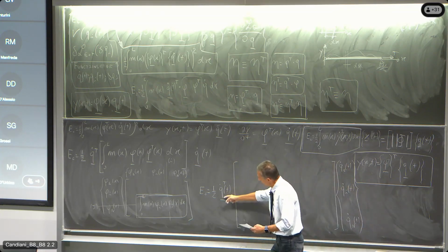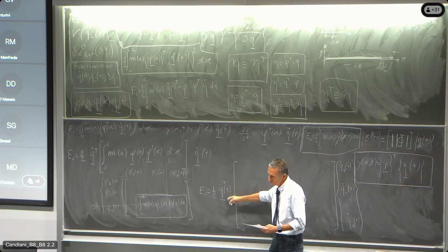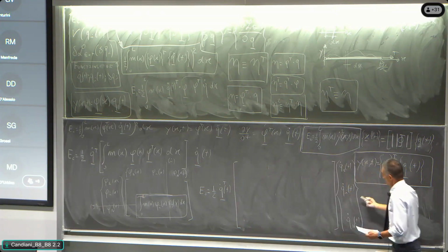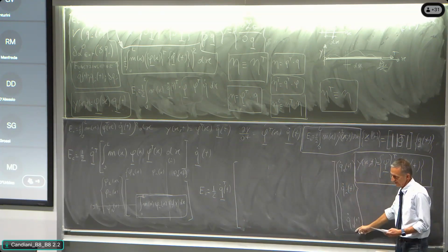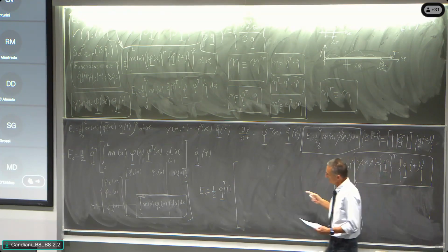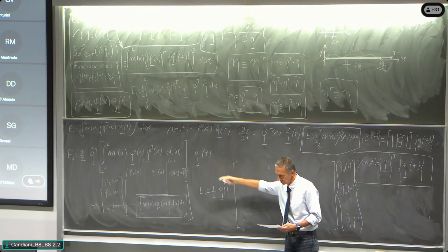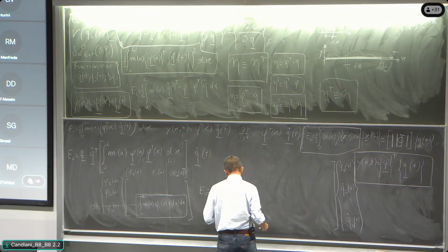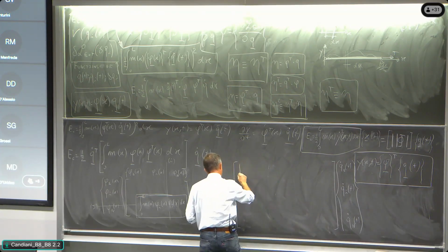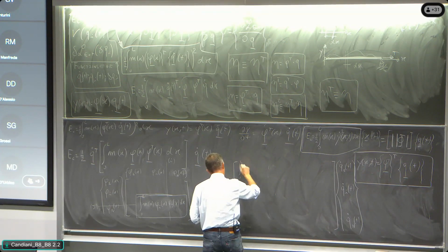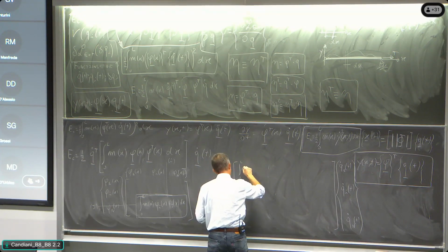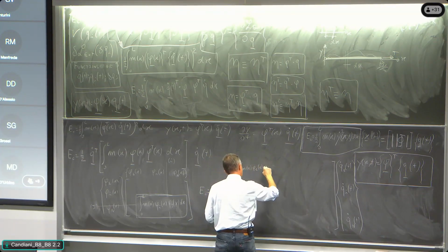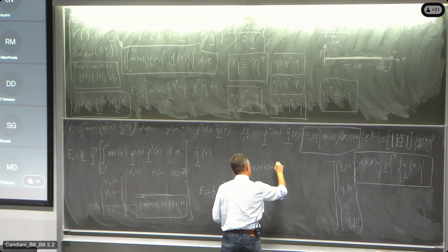Now here I do not write the vector q1 dot q2, but I write q transposed, knowing that q is the vector column, so q transposed is the same but positioned as a row. And in here I have, in the location 1, integral 0L m function of x, phi1 function of x, phi1 function of x, dx.